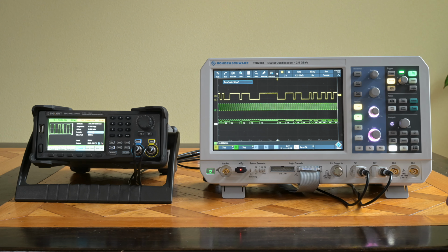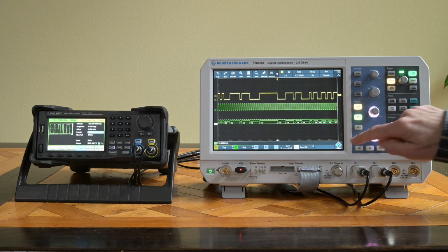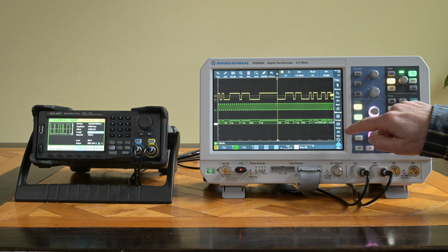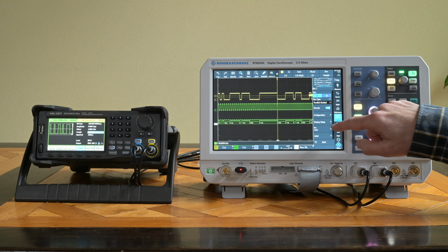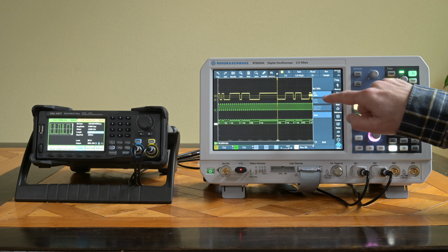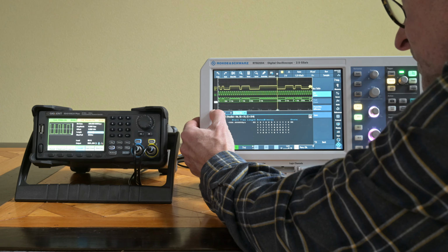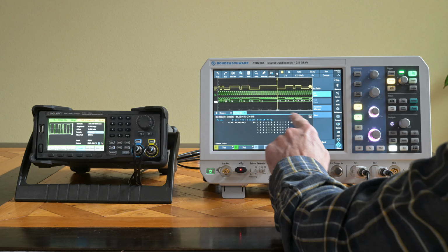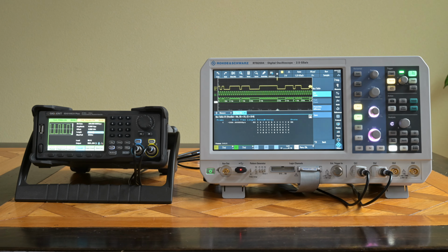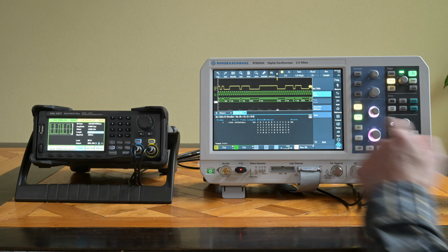And in order to decode this as values as a total, we probably want to see the bus table here. So I'm going to protocol, and I'm going to ask it to show the bus table, and I'm going to make the bus table a little bit larger. All the signals will get a little bit shorter. So here I'm getting to see the signal that I would like to see.